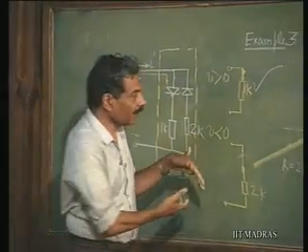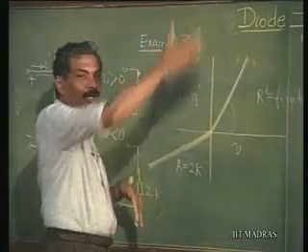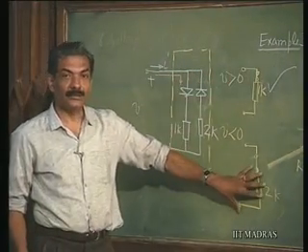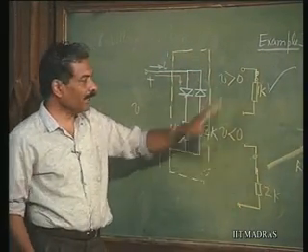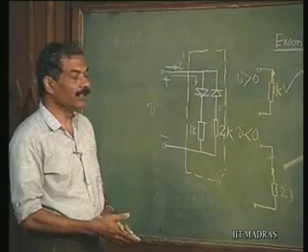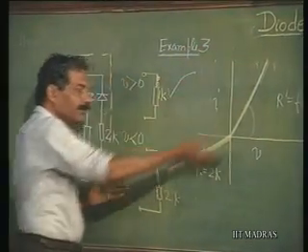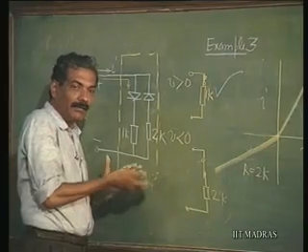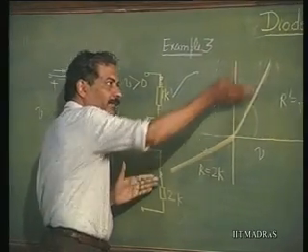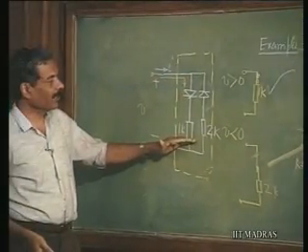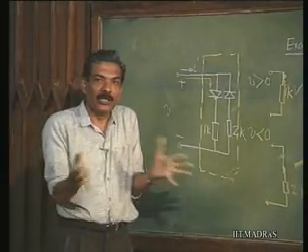So, I can synthesize a nonlinear characteristic I want purely by using diode and resistors. We will see how this is going to be useful for me to obtain any nonlinear characteristic whatever be. I will simply approximate it to some piecewise linear characteristic and use diodes and resistors and obtain such complex nonlinear characteristics.